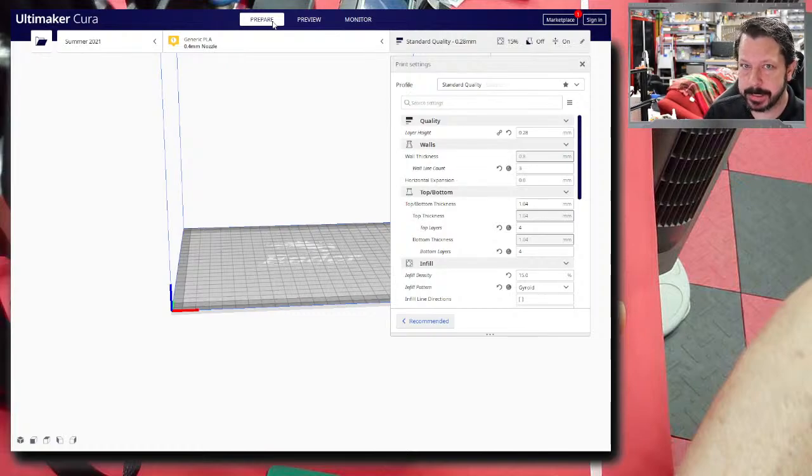Remember, one of the biggest things that cause these to not work is having something like Cura open and your USB cable plugged into your printer, and then the other terminal, Pronterface or whatever, can't access that USB port because Cura is already using it.